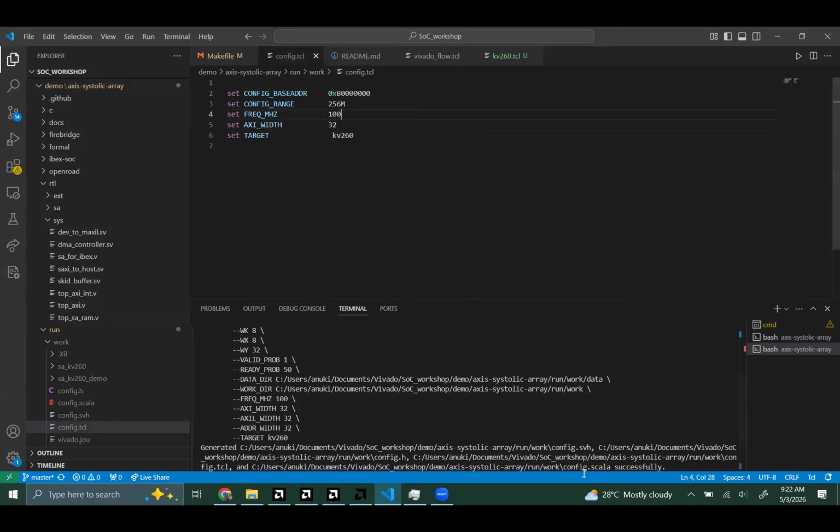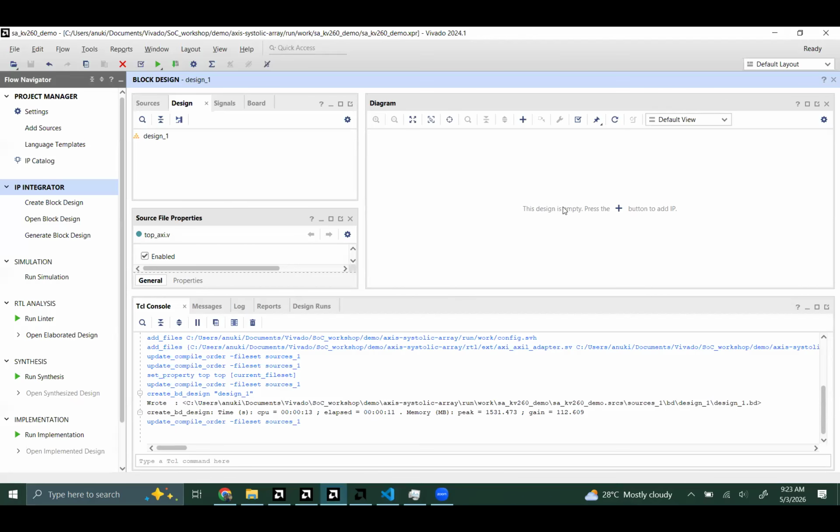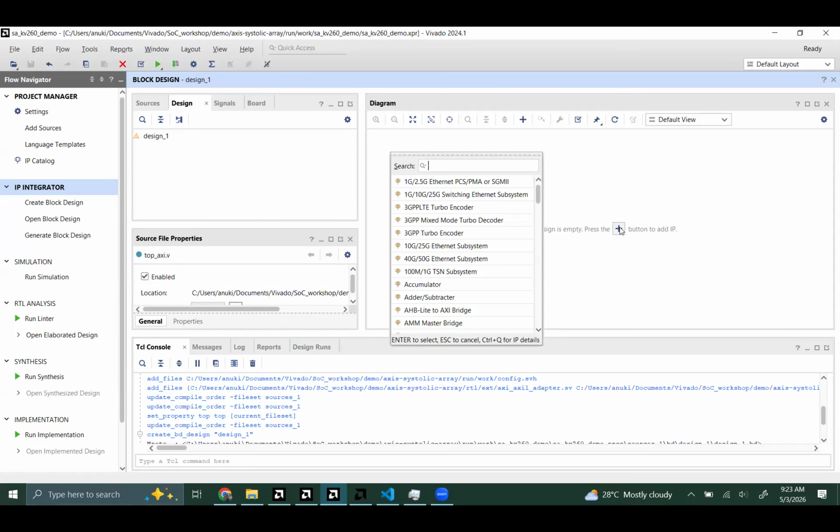In Vivado, block designs are an easier way to do those connections. It will bundle a whole port together. Like if there are 10 signals you need to connect between two modules, it can bundle those signals together so that it's much easier to connect. That's the purpose of the block design.